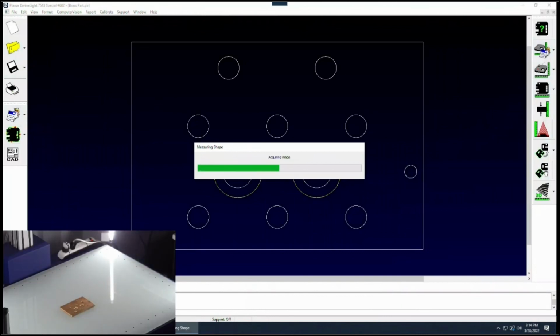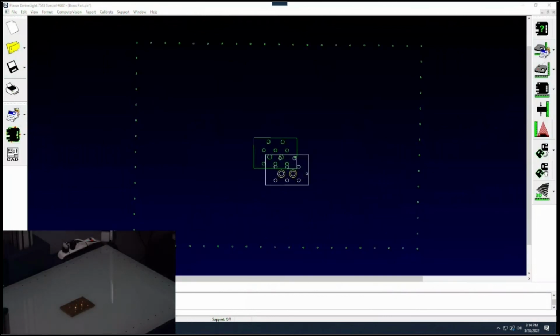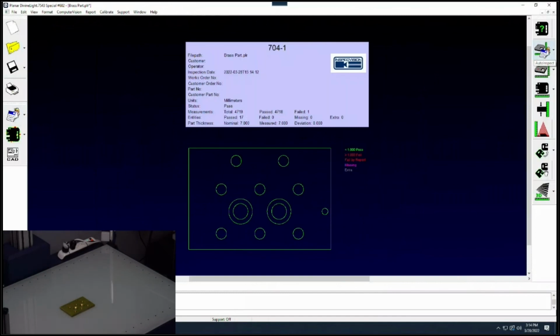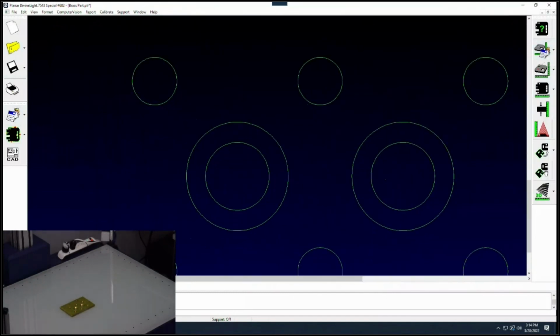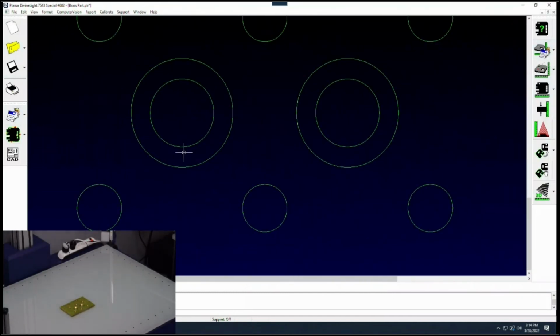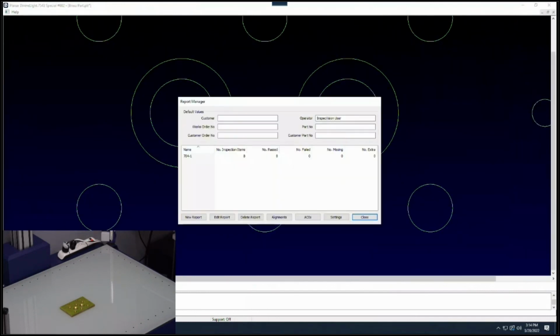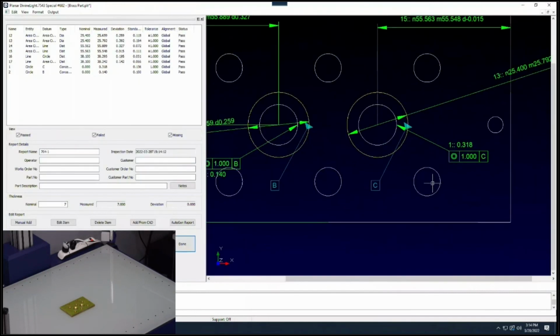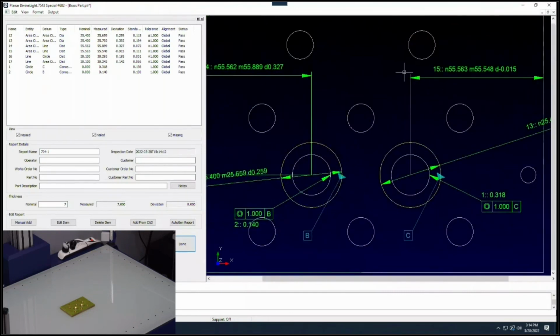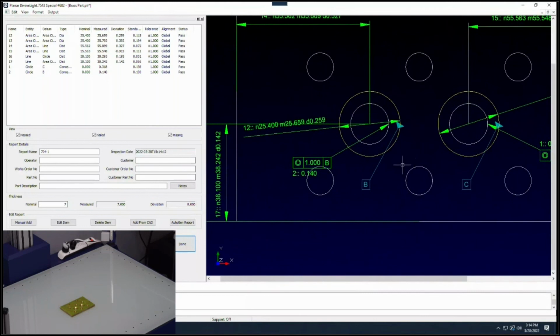Again, use the 2D, turns on the light pillars so we can see the overall, and you can now see that I've actually got 2 diameters I couldn't normally get. And if I go to my report, I can actually call out concentricity from the ID to the OD. I can get diameter, I can get distance from one wall to the other. All that information is now viable with our AOI.